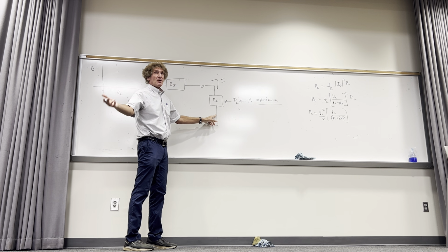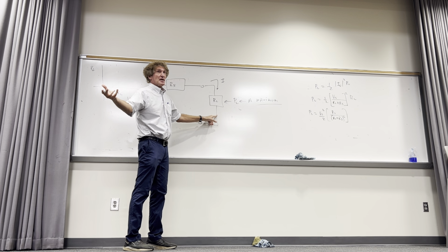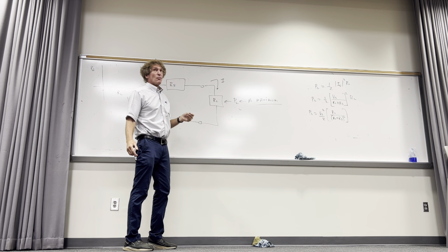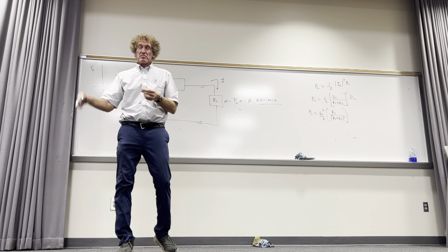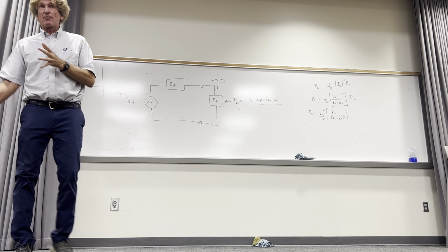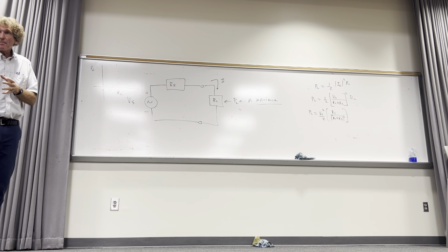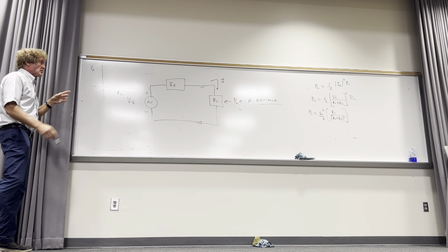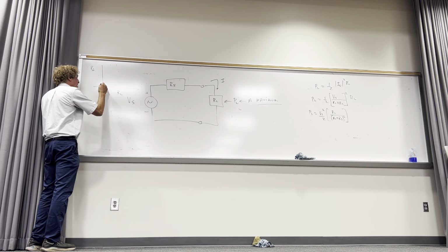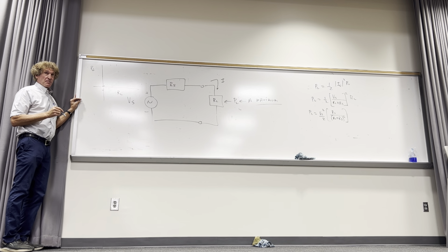What's the voltage across the short circuit? 0, right? Matter of fact, what's the resistance of a short circuit? 0. So no matter what the current is, 1/2 I squared could be very high, times 0 is still 0, right? You all follow me on that? So when the load itself is a short circuit, there's no power absorbed.